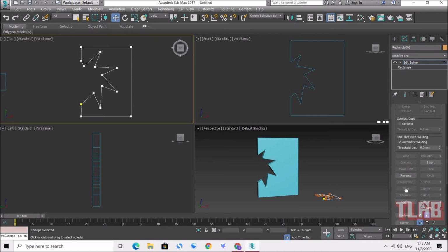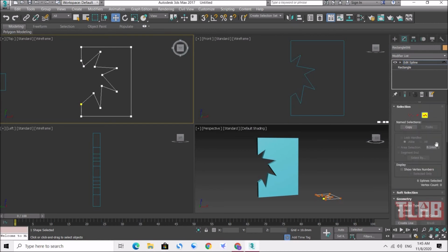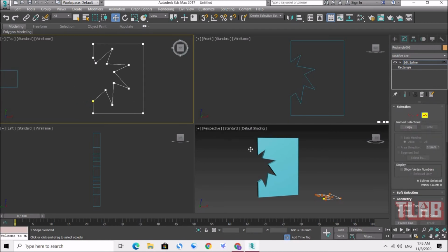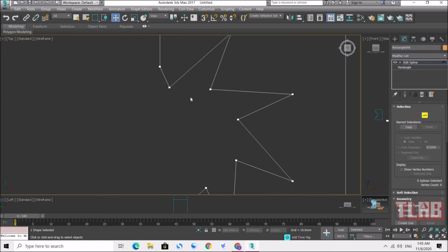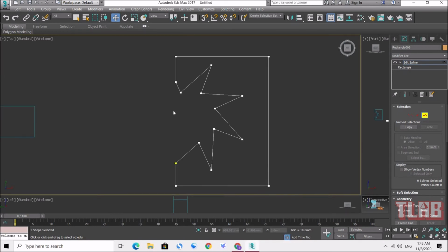So after that, Trim, deselect again. Okay, so now one more step again. Because why? You can see, I move out, I rescale the view. You can see that actually the existing object is two objects. Then you use Trim to complete the model, like the shading like this.